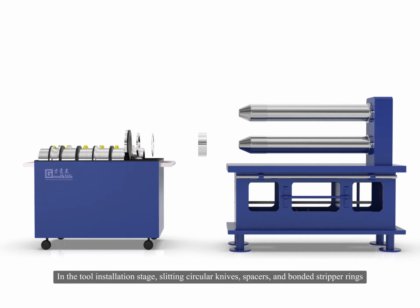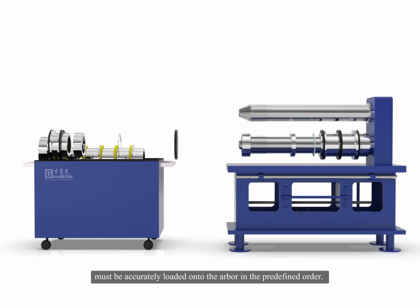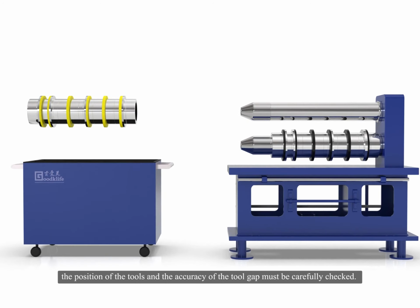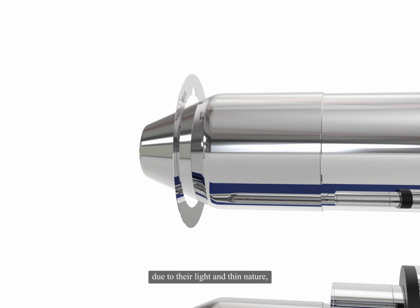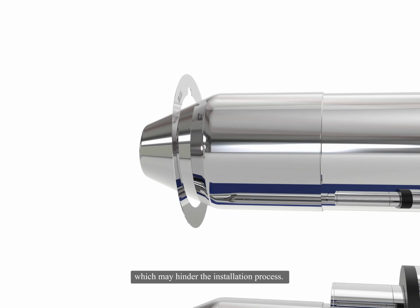In the tool installation stage, slitting circular knives, spacers, and bonded stripper rings must be accurately loaded onto the arbor in the predefined order. During this process, the position of the tools and the accuracy of the tool gap must be carefully checked. For thin spacers such as 1.01 or 2.01 mm, due to their light and thin nature, they are prone to tilting when installed on the arbor, which may hinder the installation process.